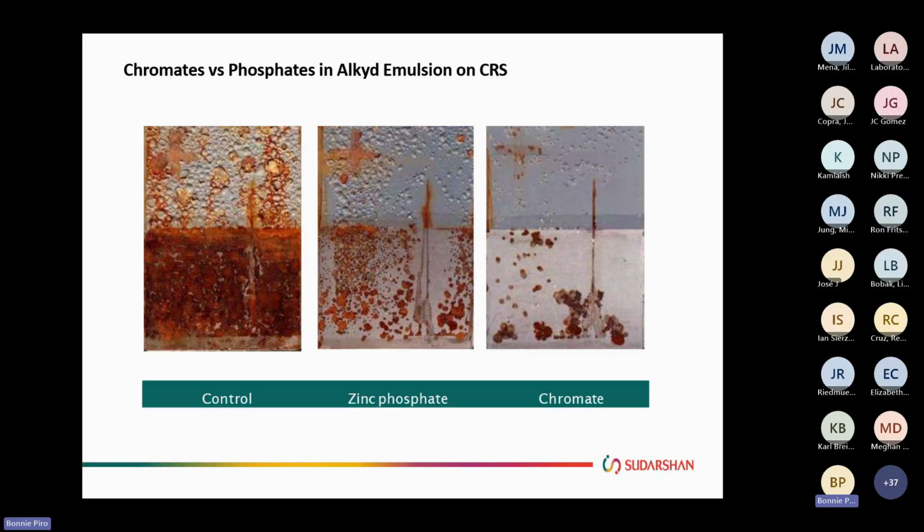And then lastly, these were developed to replace the chromates. As I mentioned earlier in the discussion here, we're always aiming to be as good as or better. In this particular case, chromates are extremely good at what they do. So the zinc phosphate alone may not be the be all to end all. So this tells us that zinc phosphate needs a sort of a helping hand or a partner to be able to get these qualities of the original chromate containing anti-corrosive pigments.